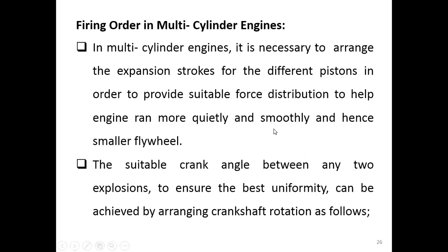And that means you can use a smaller flywheel. No need to have a big flywheel if you provide the firing order in your multi-cylinder engine properly. Okay. We need a suitable crank angle between any two explosions, because we have more than one cylinder.